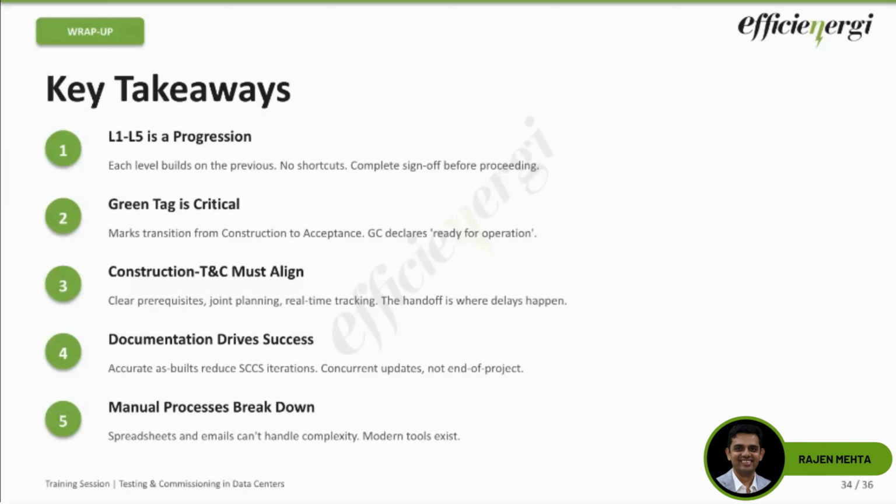Yes. So see, typically DC is always more destructive in a way, I would say, especially when you're doing hypot, because that's a stress test of your insulation. In real-life conditions, you are not going to be subjecting your bus ducts to a DC component. It is going to have an alternating frequency, right?